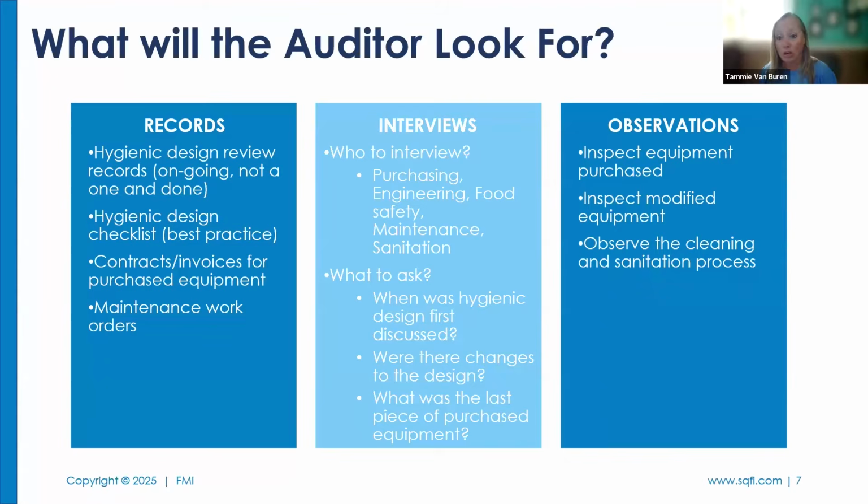And then maintenance work orders. Dan talked a little bit about modifications and things that you do internally, making sure that if you need welds, you have somebody that's trained to do a hygienic weld. So it's smooth, it's continuous, there are requirements there. And if you don't have somebody trained in that, outsource. That would be your big thing to do.